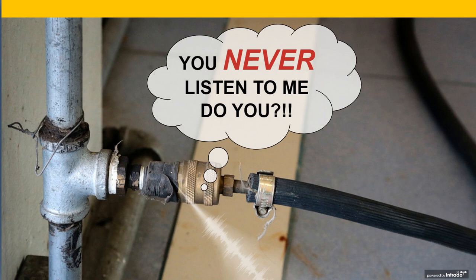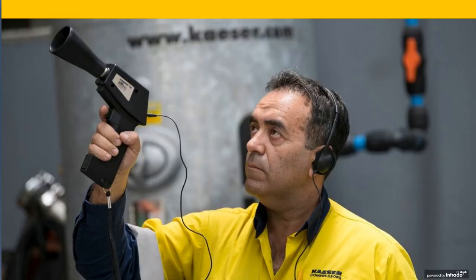If that leak is leaking 24 hours a day, 7 days a week, and your energy cost is roughly 10 cents a kilowatt hour, that's almost $20,000 a year. That's a huge waste of money. So what do we do? Well, the fact is that many of your leaks can't be heard or felt. And the best way to find those leaks is through ultrasonic leak detection.